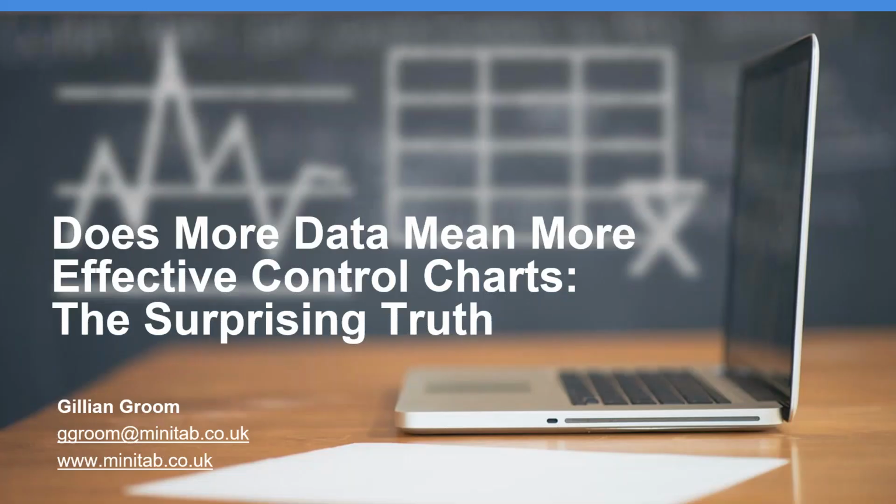So in conclusion, does more data mean more effective control charts? Well, the truth is, if you use the individual measurements that you're collecting from full inspection, it does not mean more effective control charts. It will just result in a higher than expected false alarm rate. Therefore, you still need to think very carefully about what your subgroup size should be.